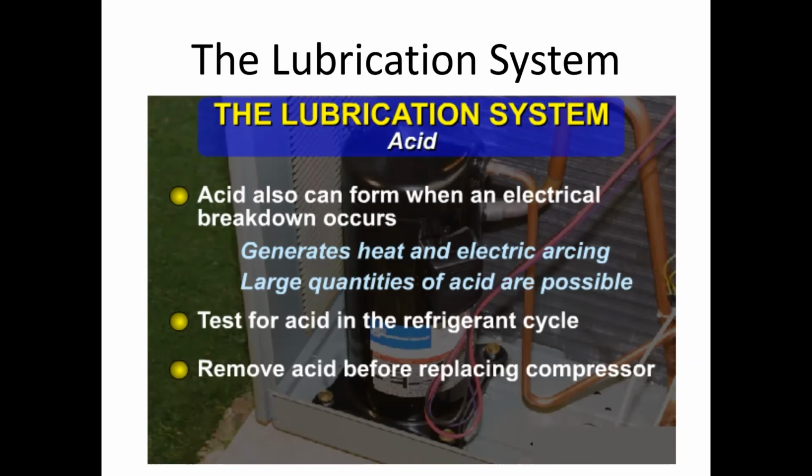That's what people refer to when I mentioned venting a pin, or your compressor plug or those connections vent or blow out of the side of that compressor, or have a serious arc, and that arc can also create the heat that creates acid in that system.